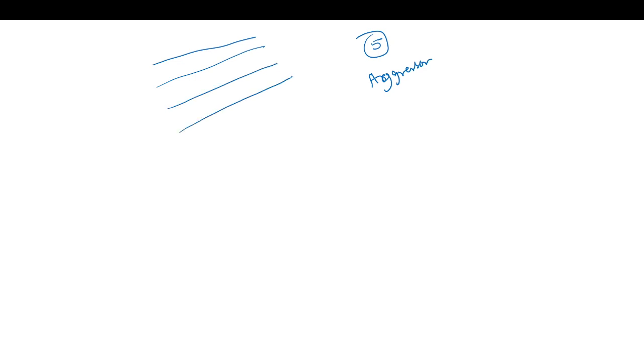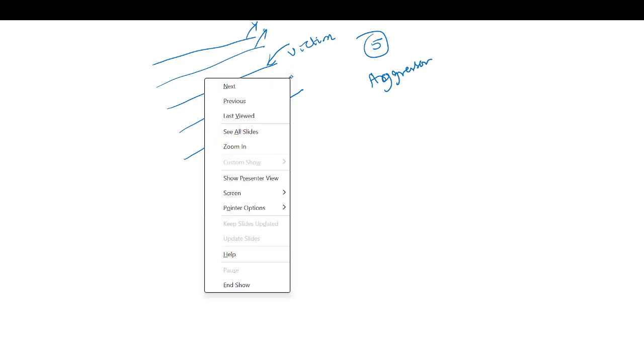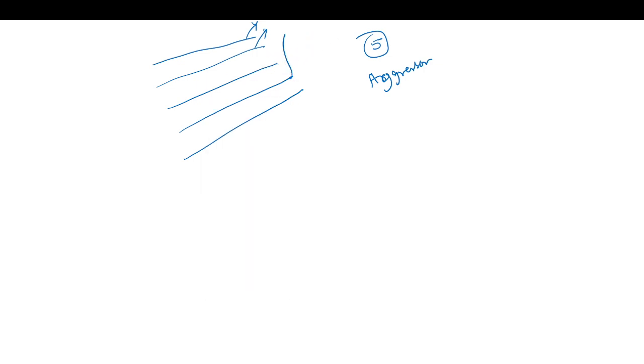So this line is the victim line and these 4 lines are the aggressor or aggressive lines. Now if the victim has to stay at 0 because of the neighboring aggressive lines, it goes to 1 for a small duration of time. This is called a glitch.